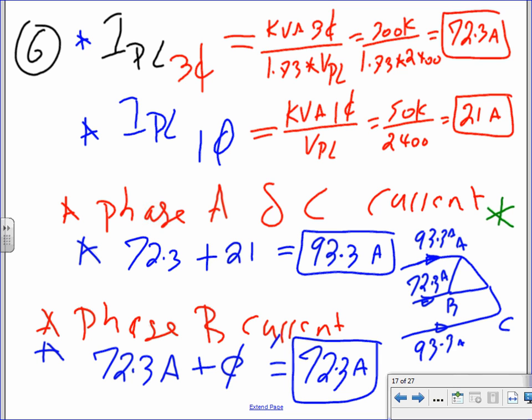If that helps you understand why, it's because we're using that center tap delta, one of the transformers is bigger than the others. Remember these values, guys, because we're going to use them to size the fuses, circuit breakers, and conductors. So you go to a transformer and find 2 conductors are big and fat and the other one is smaller, and you wonder what is going on. Remember, 2 phases are carrying more current than the third phase. That only happens in center tap delta, for the most part.